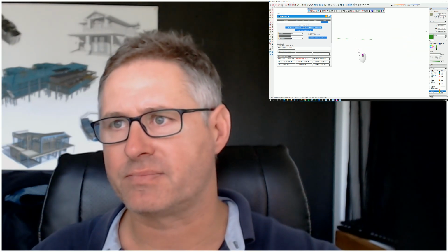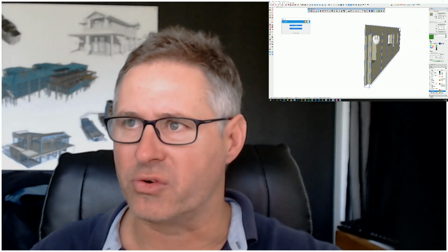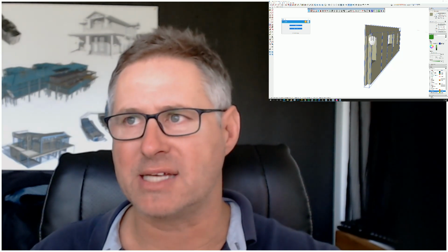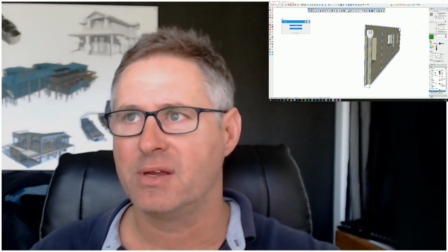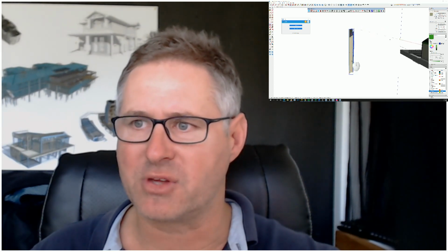Okay, right. So you'll notice the way this wall is drawn, it's not actually the way we would build it. We'd actually have a flat top plate, and this would be like a parapet, and this is covering up the ends of the rafters so that we can have our insulation come up. So I need to know about this wall before I can actually start to draw it.